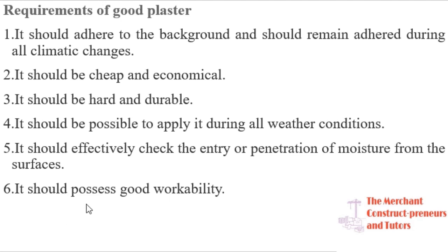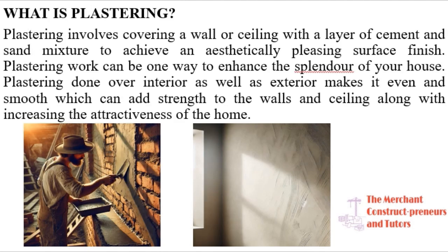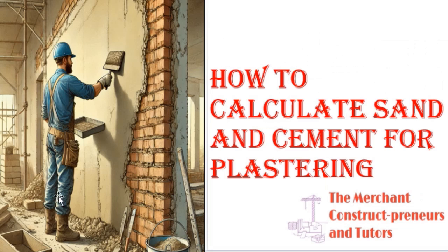Now the last one says it should possess good workability. Yes, good workability, like I explained in this image here. Once this is down here, you should not allow it to dry before you start thinking of reusing it. It should be workable. Once you are applying, it should not be hard. Some people mix plaster in large quantities at once, and before they finish what they are doing, some of what they mixed is already hard, and it will not be workable again.